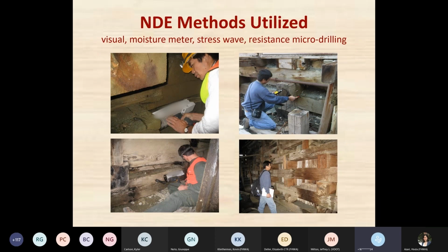Here's all the tools in use, visual inspection on the bottom right. Some of these walls were 10, 12 feet high, and some of them were only 2 or 3 feet high. I don't know if I mentioned, but there's 11 different stories in this building. It seemed like there were several additions added as they went for different stages of the process. The lower levels, if you can believe it, were wet, and they were sometimes frozen, so some of the drilling was not very conclusive in the wet wood. It's something we never drilled before because it was frozen, and we were up there in June, so it may stay frozen for most of the summer at the lower levels that are closest to the ground. The upper levels were not frozen; they were more open air. Next slide.